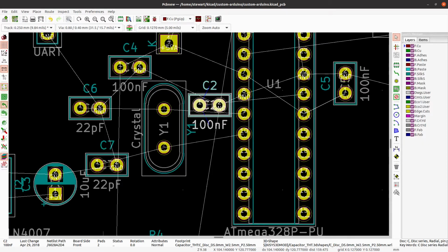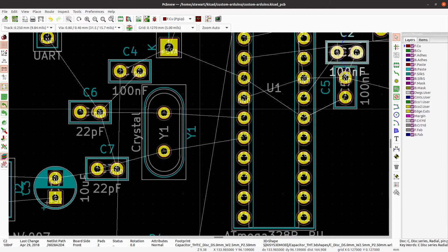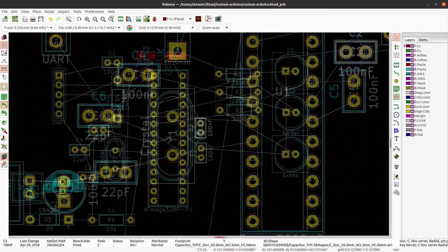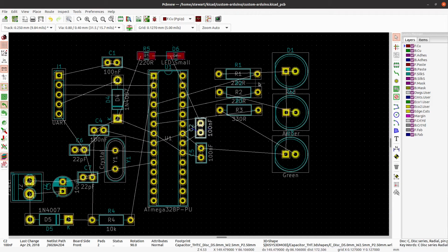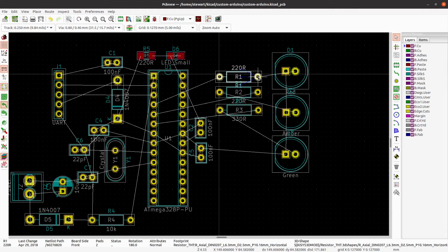On the PCB, pin 21's over here. As you can see, the wires from here go to that side, but that one, which wants to go to the diode, is at the wrong side, so just click on that and rotate it, then move it over there.